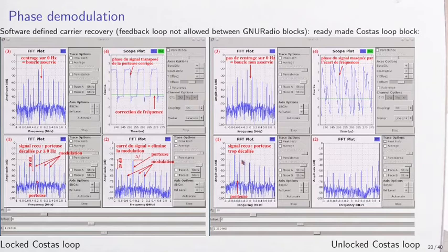If this time we shift the frequency too far, you see here that we have taken this phase modulated signal and shifted it further to the left. Well, this time the QPSK loop is unable to compensate for this frequency offset, and you are left here with the random phase fluctuation overlaid with the frequency rotations due to delta omega times t. Why is it that the QPSK loop was unable to cancel the frequency offset?